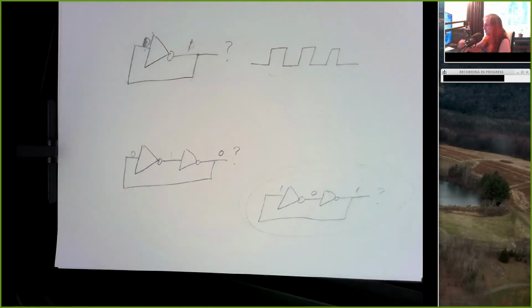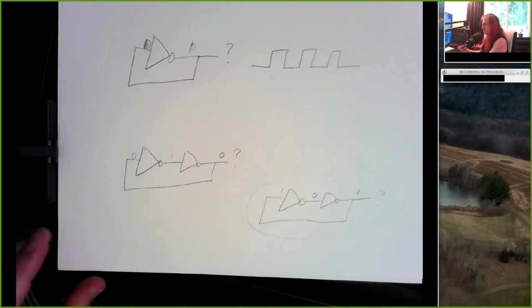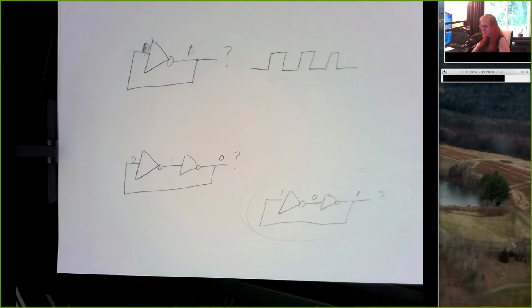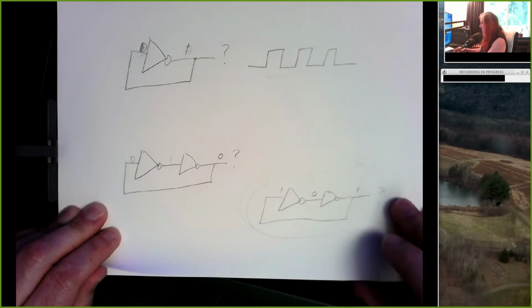This is the kind of circuitry that you find inside cache memory. When you have a CPU and it's got a certain amount of on-chip cache, it's usually built with the circuits that we're going to develop right now, which will be things called flip-flops. But the main memory of your computer does not use this. It uses something that's slower but cheaper, which is a bank of what are called capacitors. So that's dynamic memory, but this is a different kind of memory.